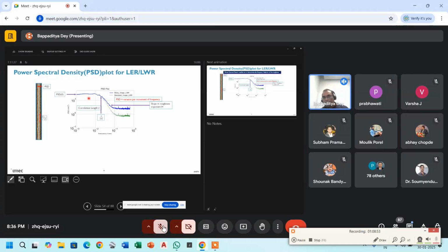So if you have your denoised image, and if you have its corresponding noisy image, of course, that you have, if you try to plot these two graphs, in the low frequency, that has to be exactly overlapped. And that will guarantee that you have not changed or induced a digital artifact into your denoising mechanism, which all the earlier research methods failed to do.